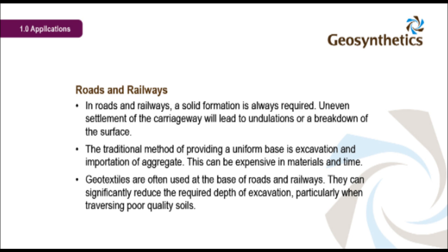In roads and railways, a solid formation is always required. Uneven settlement of the carriageway will lead to undulations or a breakdown of the surface. The traditional method of providing a uniform base is excavation and importation of aggregate. This can be expensive in materials and time.